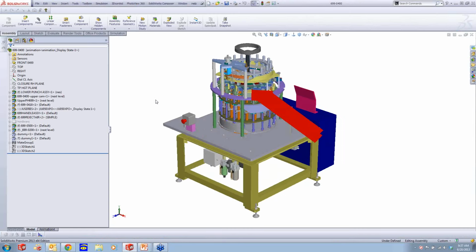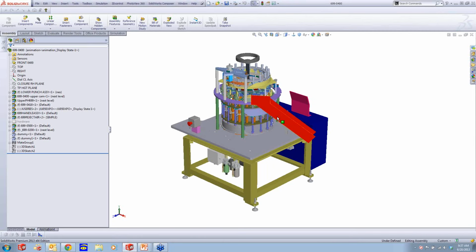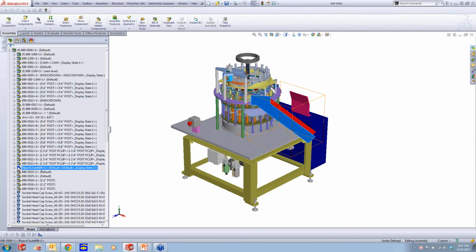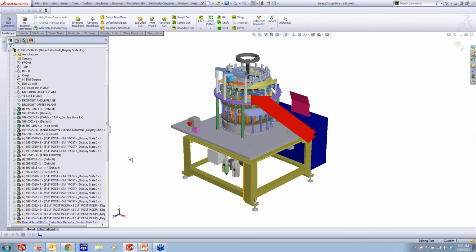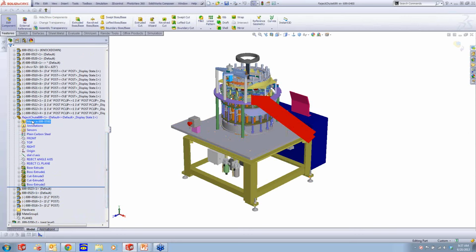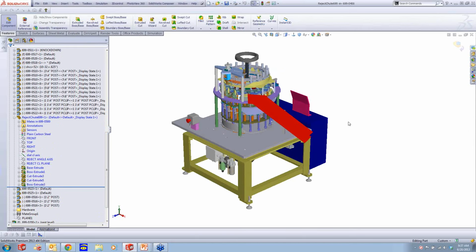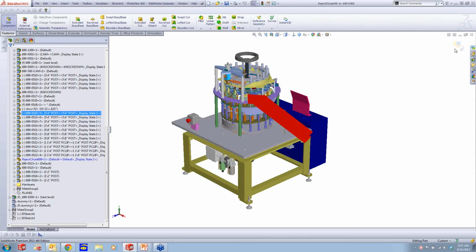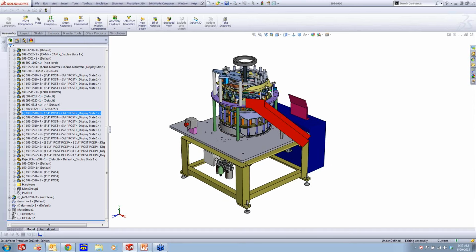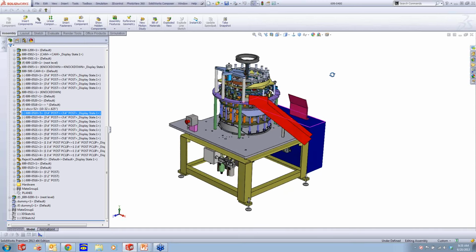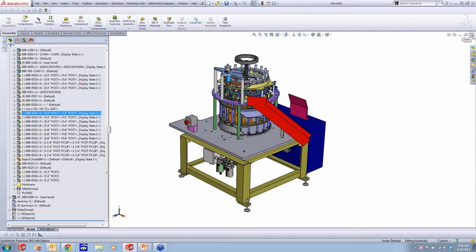And we're done. So a lot faster to load. Essentially, what you're going to see in the feature manager is you're going to see these little icons over the parts. There's no feature data there until I actually go to do something with it. So if I need to modify this part, I can edit that part, and now all those features show up. Okay, so it's there on demand. There's a couple other things. I can still show edges of the part and things like this.